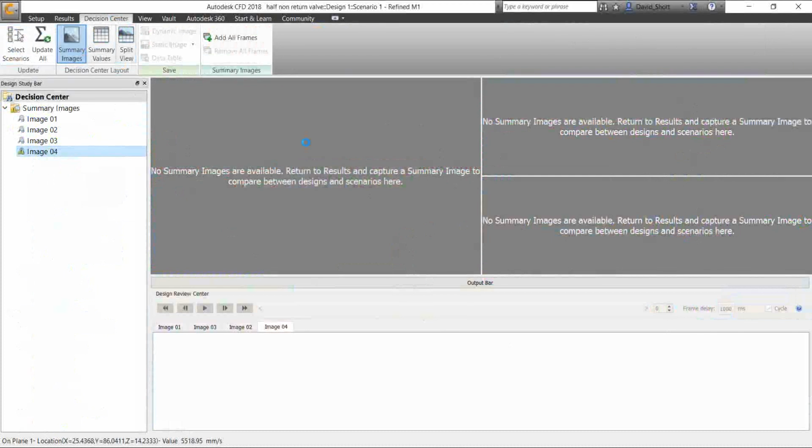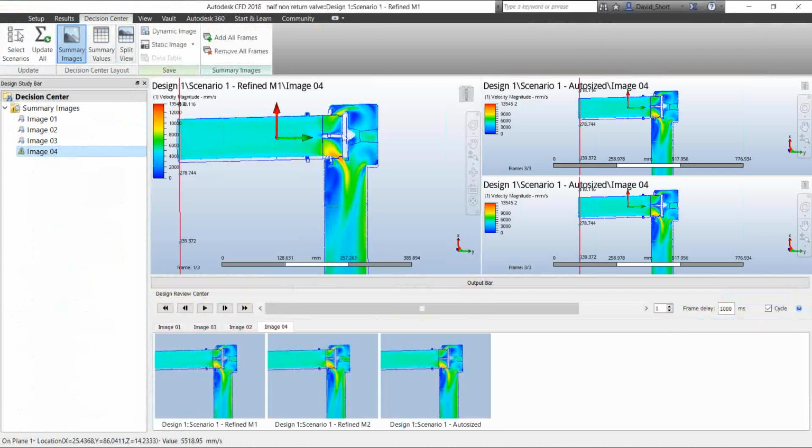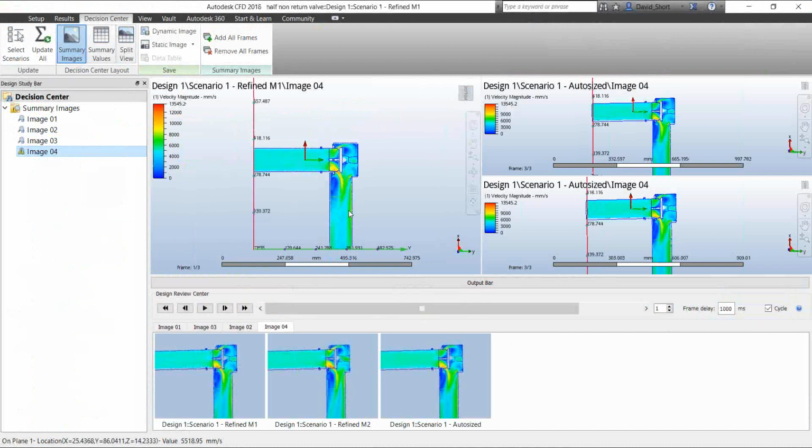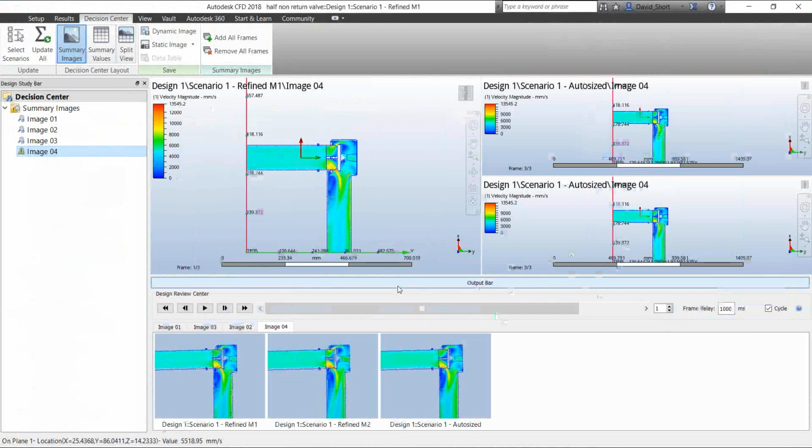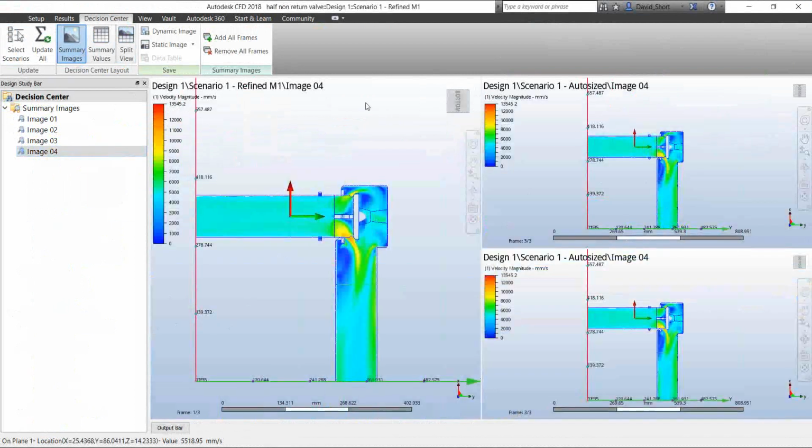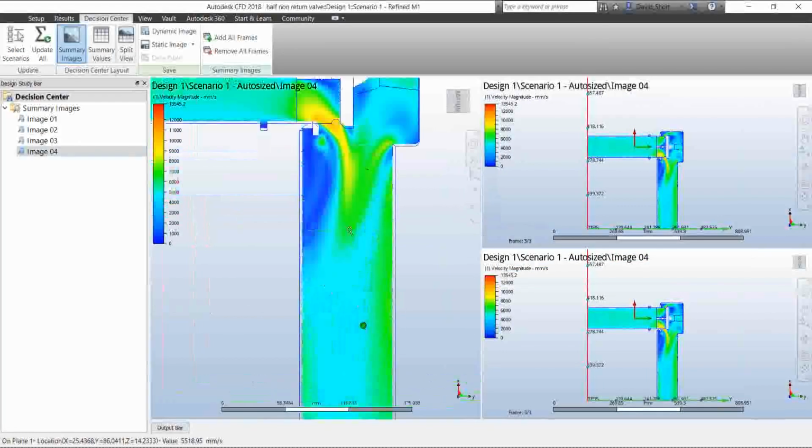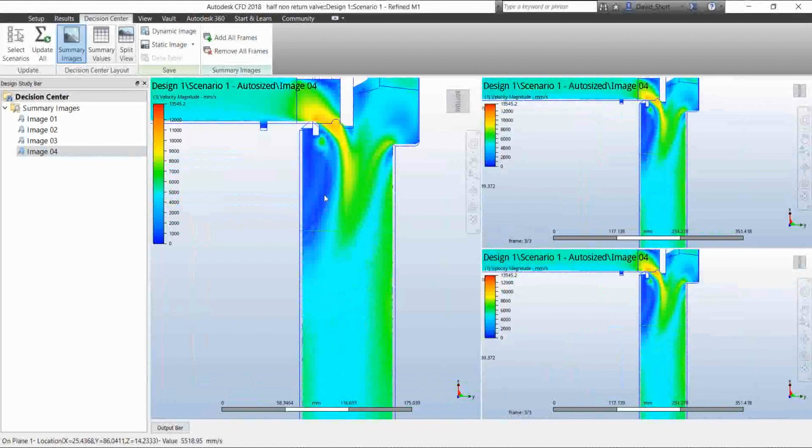Using the cut plane is really nice because you're not looking at that slip symmetry face in the global results. You're actually down inside, as if you're cutting right down the middle. If we look at the auto-sized mesh, you can almost make out the mesh here. Exactly, and that's what Matt was talking about. We know that isn't physical. There is no mesh in reality, so we shouldn't be able to visualize the mesh in the results. It's due to too-high gradients.